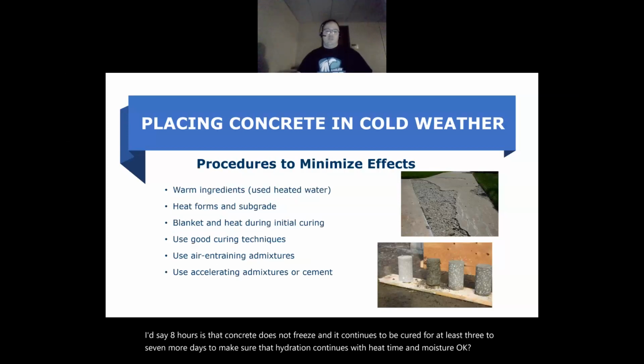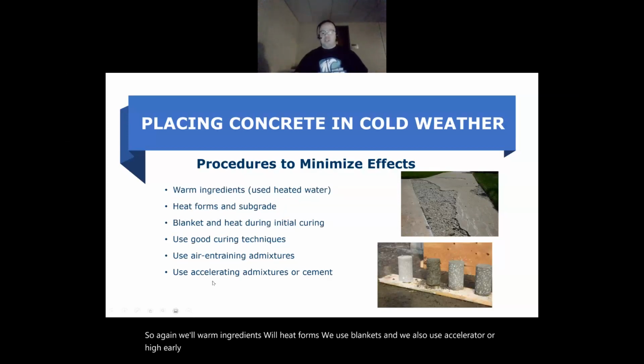So again, we'll warm ingredients, heat forms, use blankets, and also use an accelerator or high early mix to help increase the hydration of the cement to make the concrete.